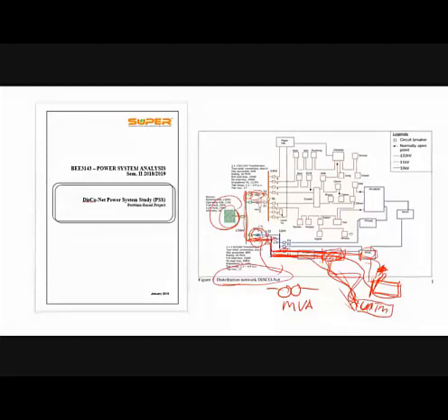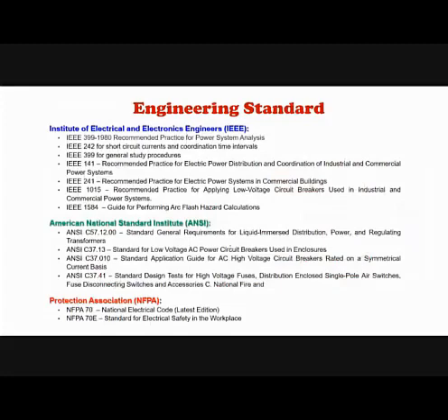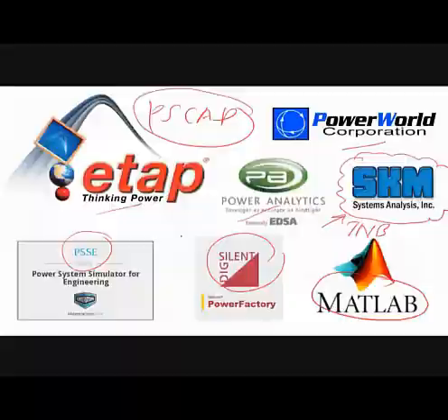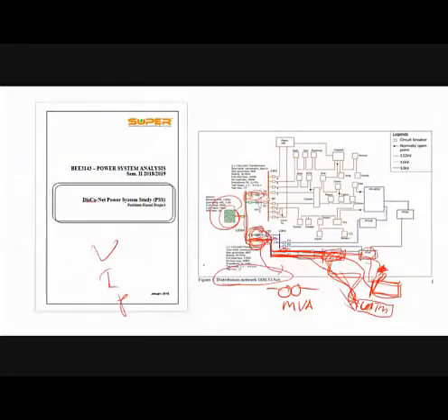And then we have to calculate current, voltage, power, and so on, so that all the equipment is well selected and capable of supplying power to the new loads. Okay, that's all power flow analysis is about. That's why power flow analysis is the backbone of power system studies. Before we do the fault analysis, we have to do the power flow first.